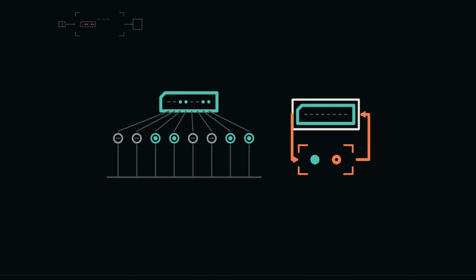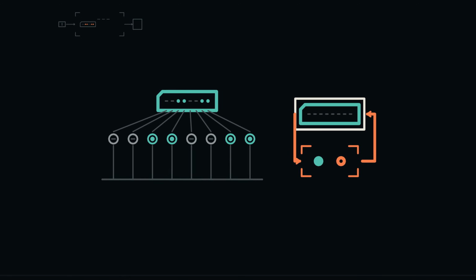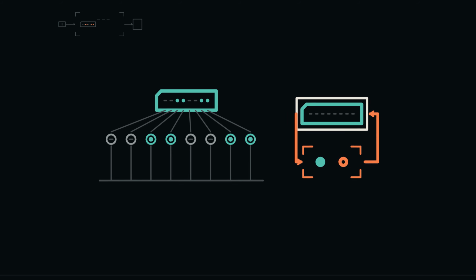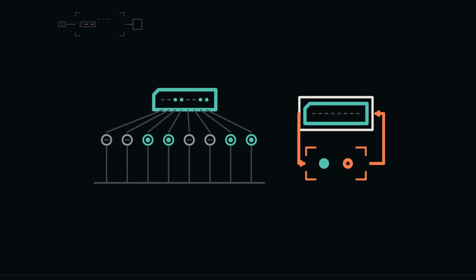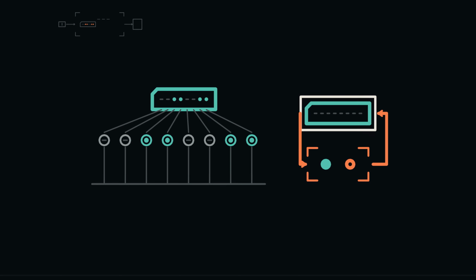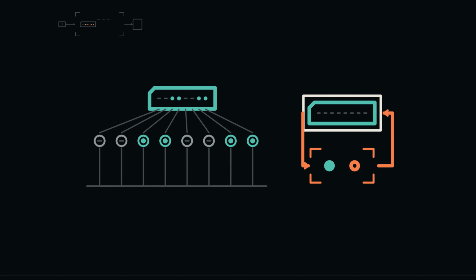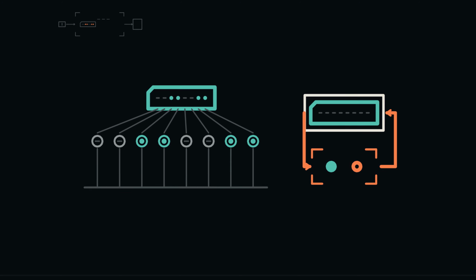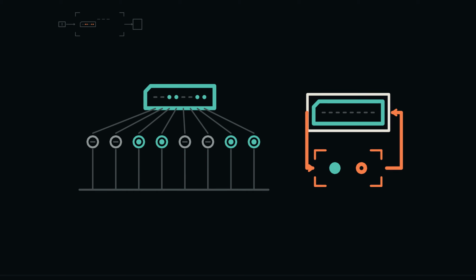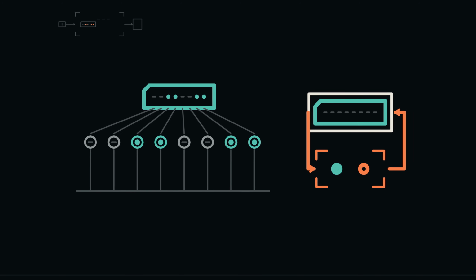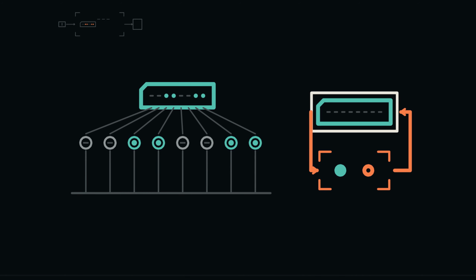An odometer gives the everyday pattern. Its rightmost wheel advances first. When that wheel passes its final digit, it returns to 0 and causes the next wheel to advance. For our counter, each position has only 2 states rather than 10. Starting at the right, trailing ones return to 0 until the first 0 becomes 1. The analogy maps positional carry. It stops at the mechanism. Our stored bits commit under an edge contract, not as visible decimal wheels turning one after another.